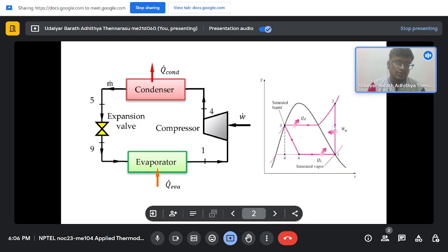Even here, a similar thing we can do is bring that cycle inside the vapor dome. In that case, we can get an isothermal condition in a condenser or an evaporator. That is possible if you bring it down into the vapor dome or two-phase region. But the problem there again is that the compression and expansion would have to happen in the two-phase region, which is very difficult.